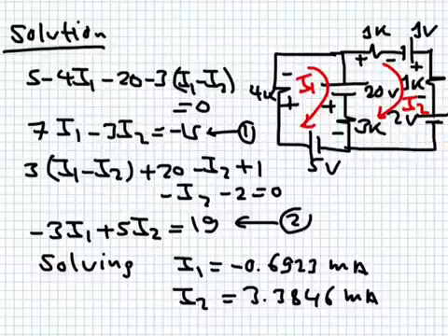Okay, so this is the equation of the second loop. Again, we'll collect all the coefficients of I1, I2, and so on, and then we have to put them in order. I'm stressing this again because this can cause trouble if you're not paying attention. Your matrix A will be wrong, and then when you try to solve it using a determinant, using a calculator, you end up with a wrong answer. So you always have to keep the coefficients in the form I1, I2, and I3. They have to be in order.